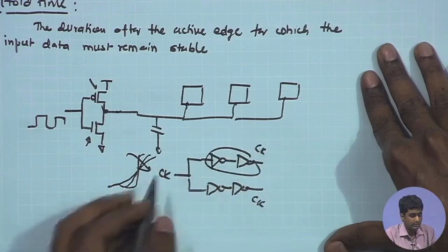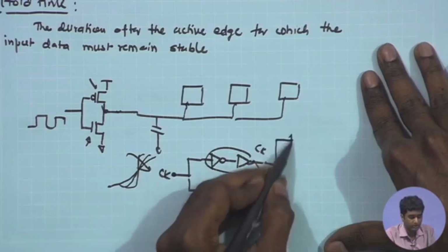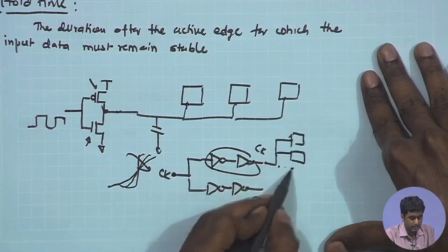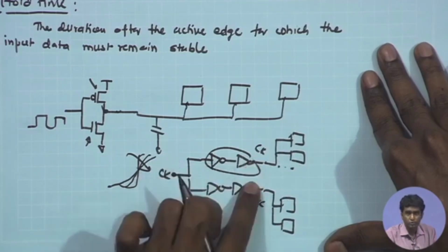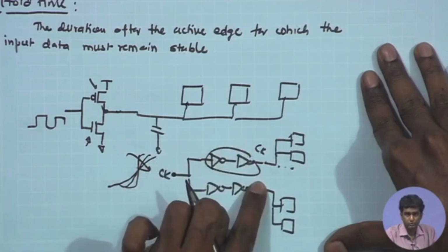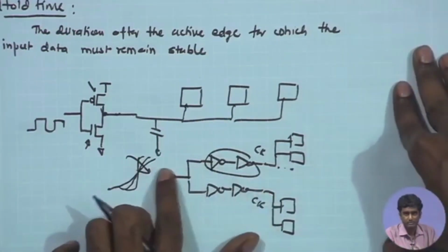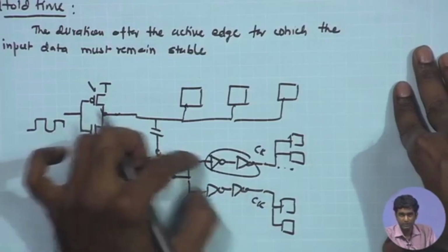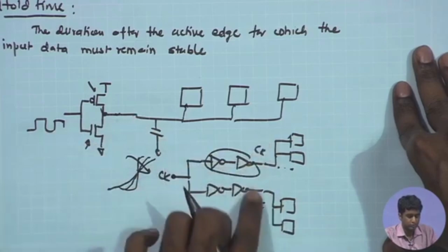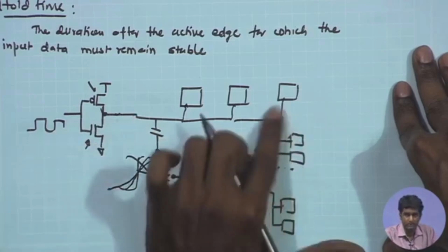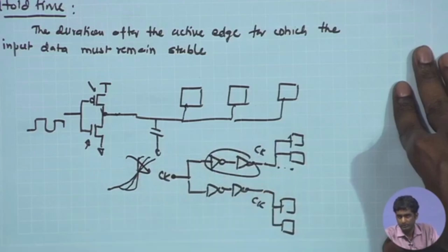So, in that case, rather than the one single clock driving too many blocks, I can have effectively two clock sources. So, I have divided the single source into two sources, and therefore, their effective load capacitance will be halved. So, a digital signal or digital clock can always be buffered. You can have bifurcation, and then you can have two sources driving half the loads each, and as a result their fan out, their total load capacitances, will reduce.